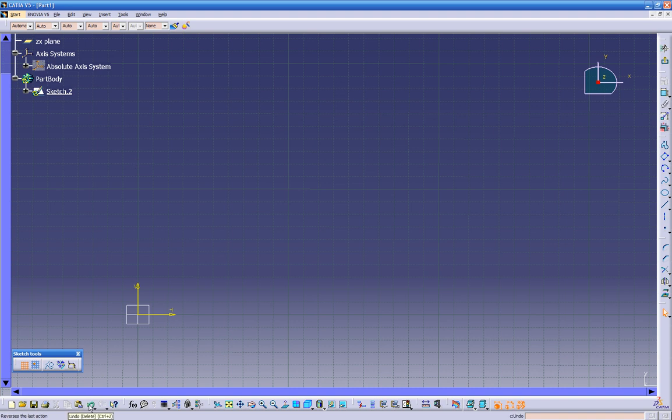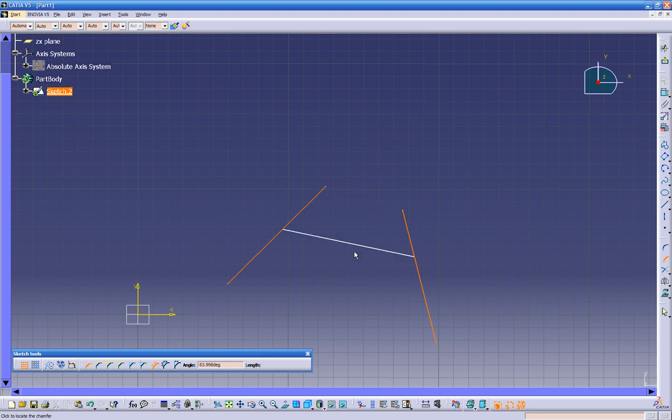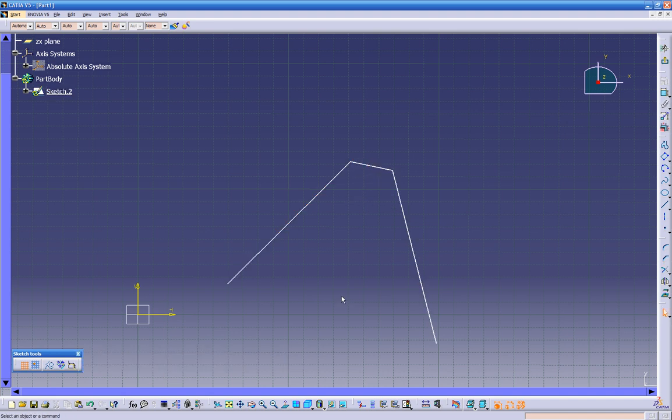We have it right down here, undo, Control Z. It's a short key. So let's give it one other try on this. Where's this chamfer? Let's give it a try. The chamfer works the same way as corner radius. Let's undo it, Control Z.